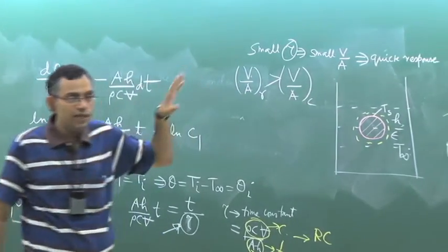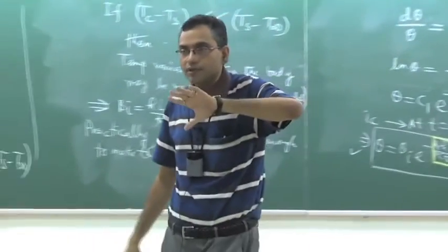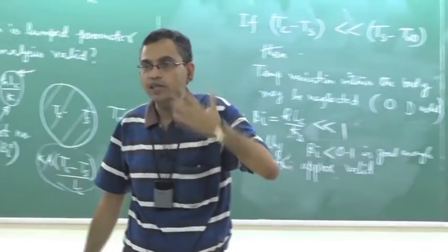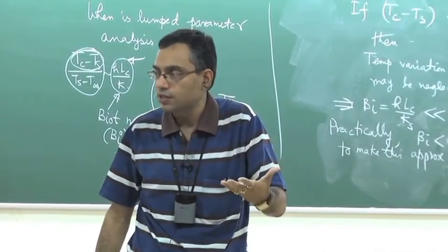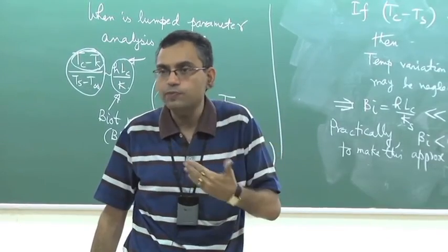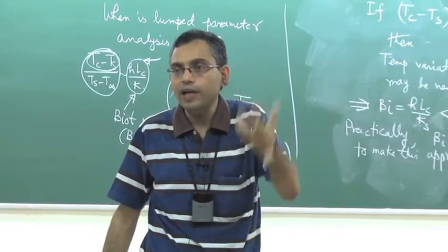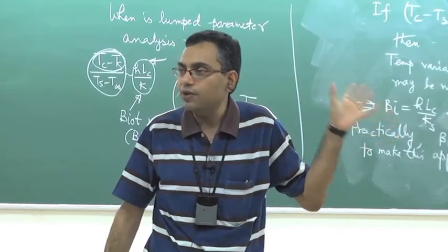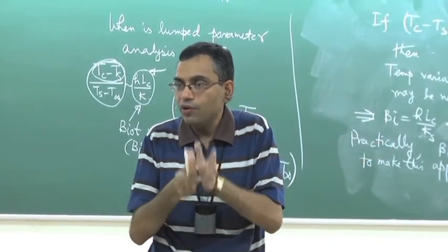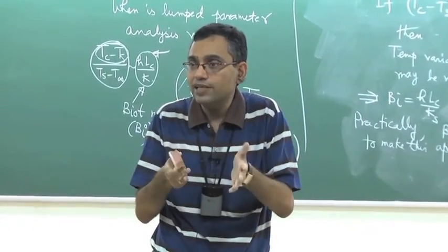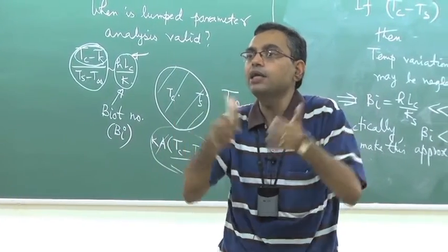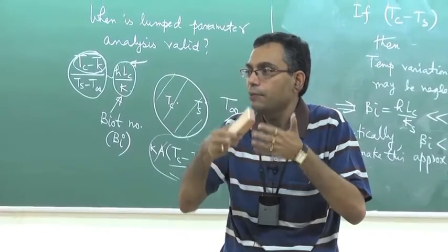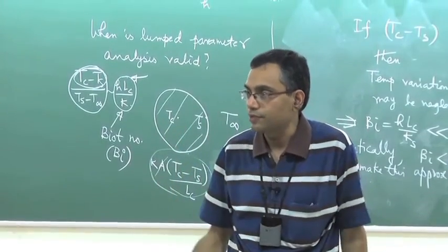So classically, manufacturing processes or studies in manufacturing in many cases have been experience based. Before the science of this was properly known, people from experience found that this should be the case for the riser design. So now you can see that the rules which are taught in manufacturing processes can be fundamentally derived if you think of a mathematical analysis following heat transfer.